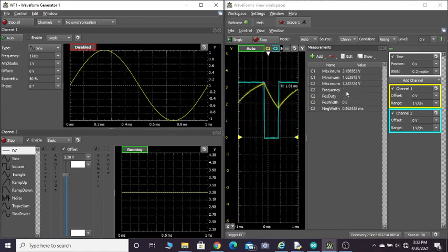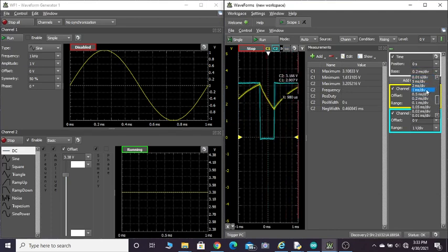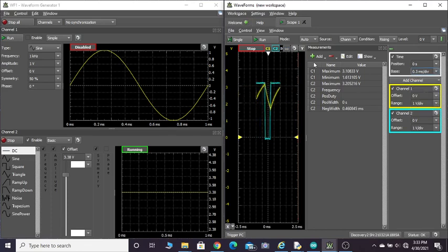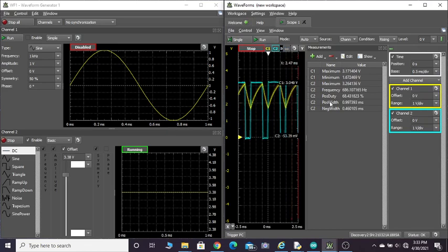You can see the frequency is the least one. I can stop it and then measure. Why it's not coming is because, let me slightly increase the number of cycles. Let me just make sure that I have more clarity. I can see the width has increased to 68%, but still you can see this is 0.48, 0.46, almost the same. Meaning, whenever we change the control voltage, the negative bit is always constant, only the positive bit changes. Even if the positive bit changes, the overall frequency will change.